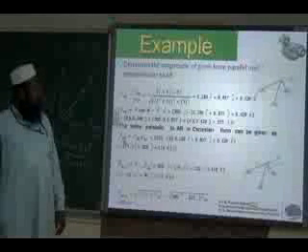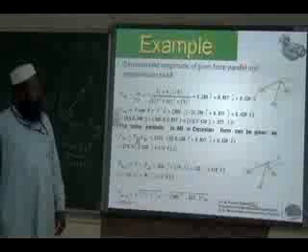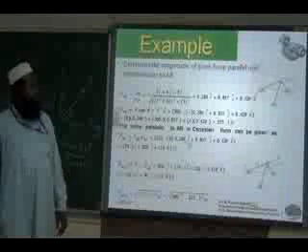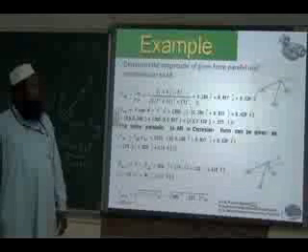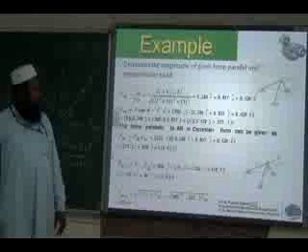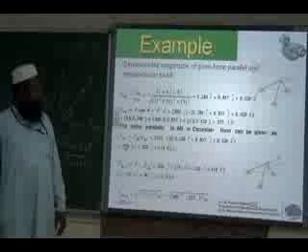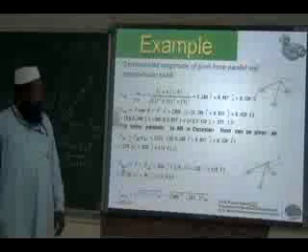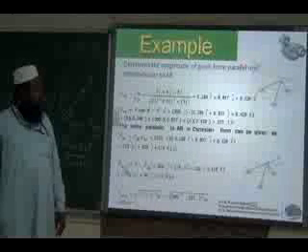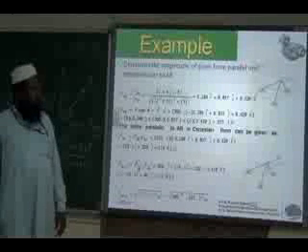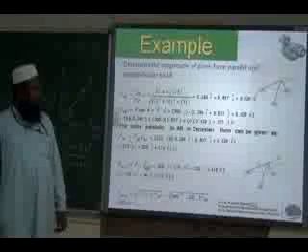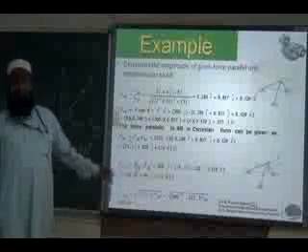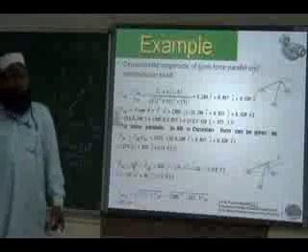Now, in order to find the force, we multiply the scalar part with the unit vector. So 257.1 is multiplied by the unit vector, which we found from our first step. So we got the force FAB in Cartesian form. And you can find the perpendicular force by vector subtraction, because FAB parallel plus FAB perpendicular will be our resultant vector.